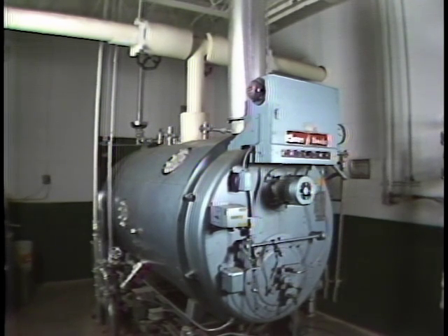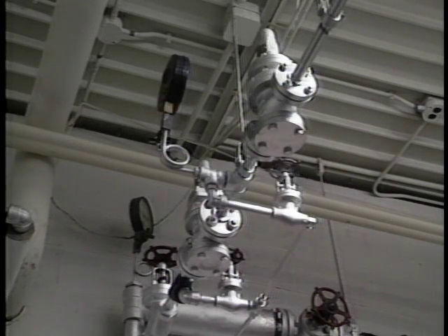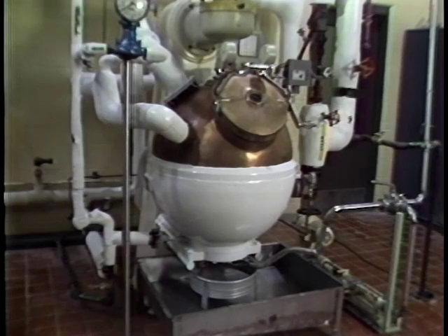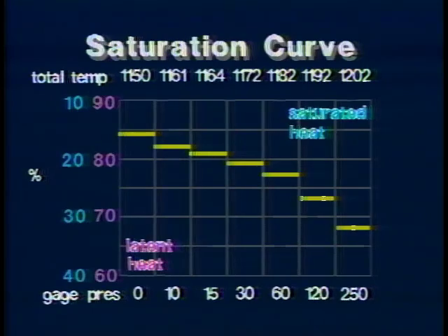The steam generated in this boiler is normally distributed at a relatively high pressure. The pressure is then reduced moderately when the steam is used to provide power, further when it is used to heat a product or for comfort control. When steam is used in a heat exchanger, the pressure is reduced because more heat is available for transfer from lower pressure steam. The total amount of heat contained in steam varies little regardless of pressure.